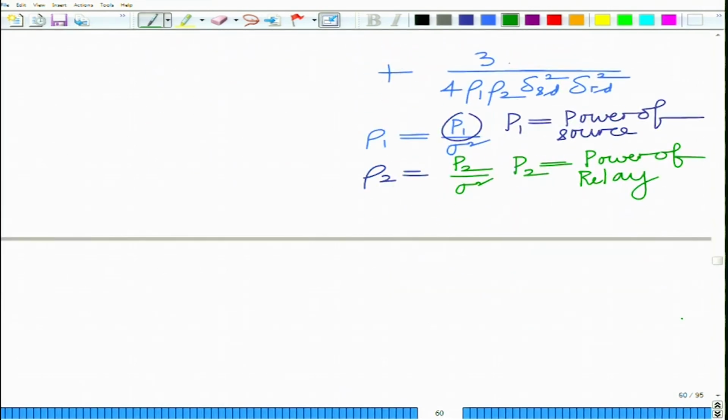Now we want to make an optimization problem where we minimize the bit error, the end to end error rate. Of course, we cannot just simply minimize it, because minimizing the error rate simply means increasing the power infinitely, and when the power becomes infinite, the bit error rate becomes 0. Naturally that is not what we want, so we minimize this subject to a constraint, because the transmit power cannot increase infinitely.